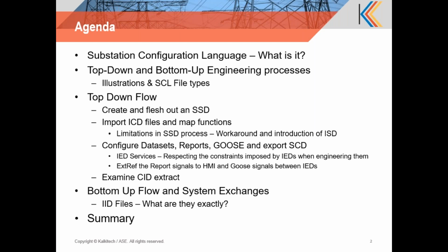We'll then flesh out all these illustrations with a demonstration using our ASE61850 suite tool, the SCL Manager. We'll start with the classical top-down flow. We'll create an SSD and specify the logical functions. Then we'll move on to import ICDs to meet those specification requirements, and we'll map the functions from the spec to the devices.